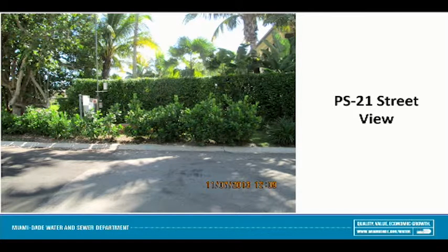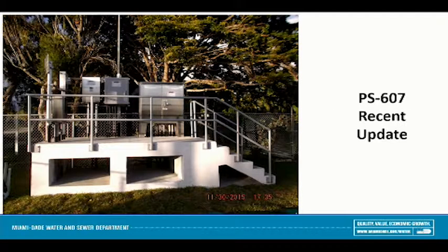This is how that station looks today. We have planted some landscaping in front. You can see the house in the back. You can see the roof. So it's right next to it. It's within the property. So this is a pump station we did recently. And we will look at this to see, well, can we fit this there? This one is not right on the coast, not too far from the coast. And it was not really done to protect for sea level rise. The elevation was 7 feet. So all we did is we brought it to today's standards. So basically, base flood elevation plus 1, to a total of 11 feet. We had those holes at the bottom so water can flow through.